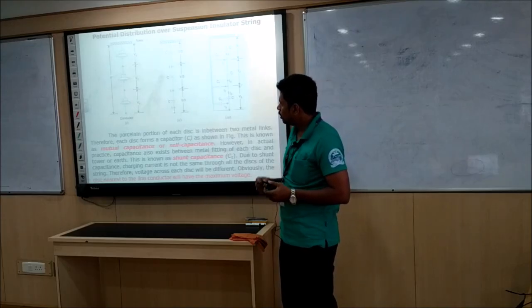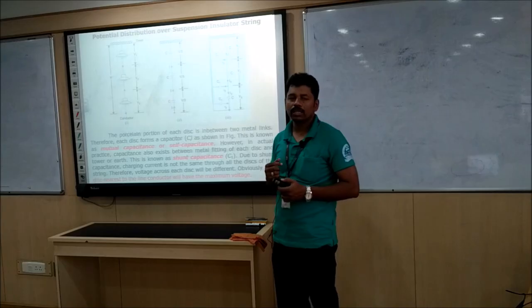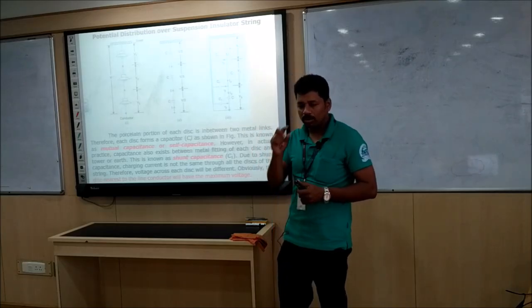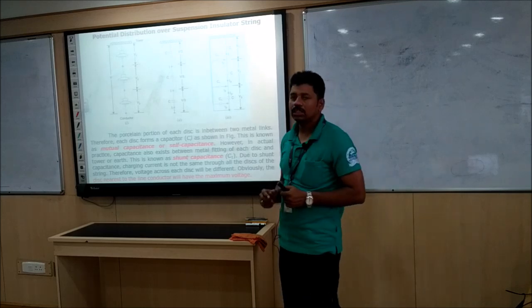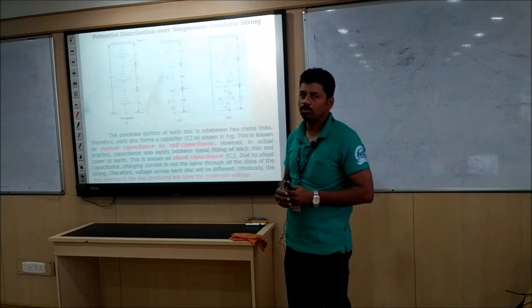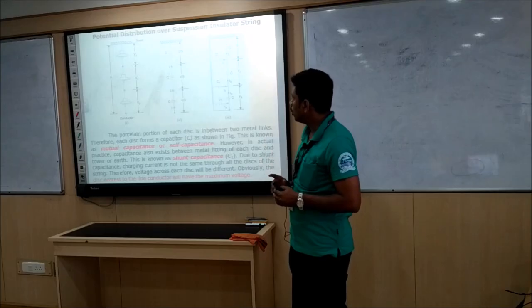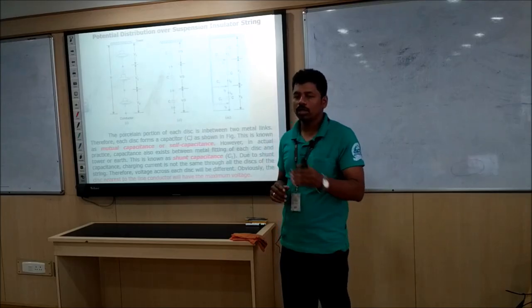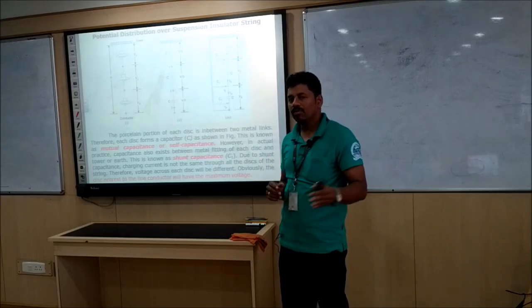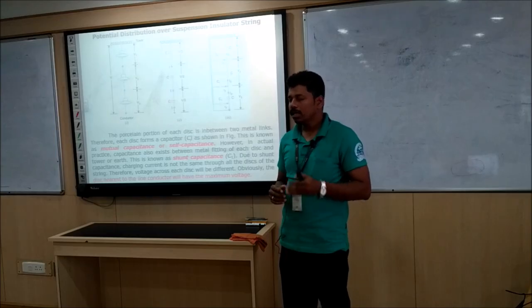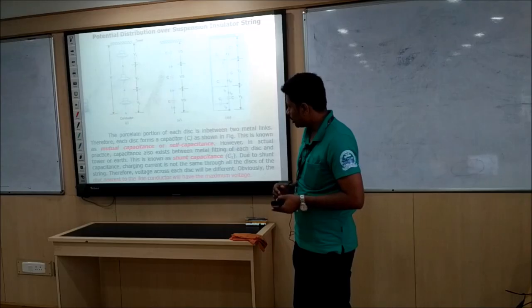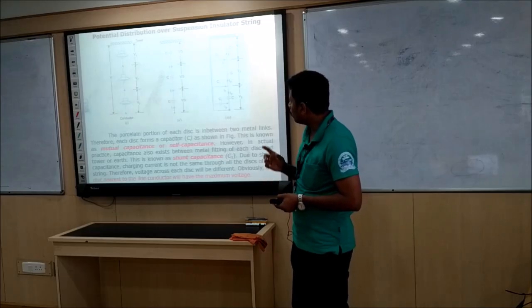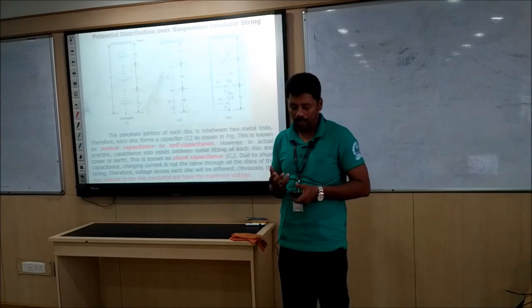This is because, in the second diagram, we can see that only self capacitance is there in the picture. If only self capacitance is there, then the voltages are equally distributed. But there is a virtual capacitance between the line supports and the midpoint of the conductor, that will form a shunt capacitance called C1. Due to that shunt capacitance C1, the uniformity of the voltage distribution is not there.